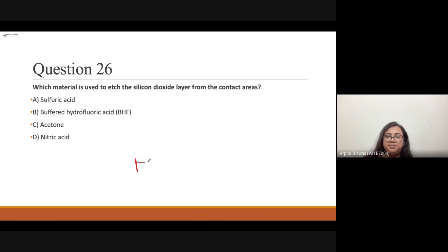Like there is a silicon, then silicon oxide, and then the micro heater is present. And in the micro heater, there is an electrode pad, okay? And on the pad, there is a silicon dioxide layer. Initially, the silicon dioxide is totally deposited, and after using the photolithography process, they have used positive photolithography, and the portion we don't want is removed by the developing process, and then we dip this wafer to remove this portion.